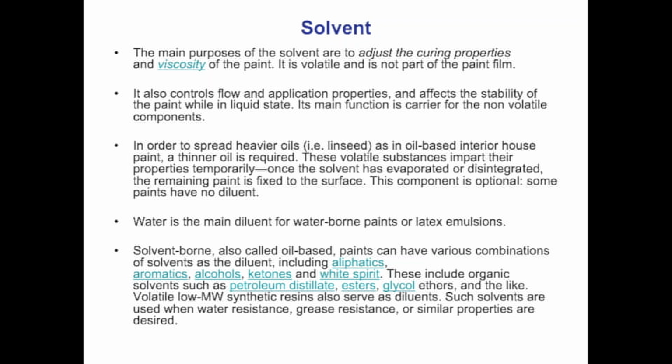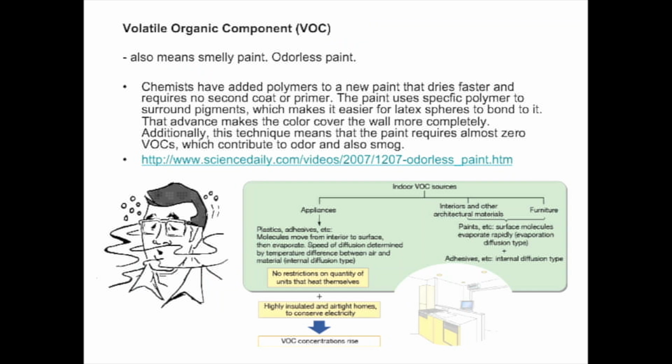Now, there's a lot of concern these days about volatile organic compounds. So for sure, a paint that smells includes volatile organic compounds, including the solvent that gives it an uncomfortable smell or feeling when you have a newly finished paint procedure. So more and more countries in Europe and other countries, including the direction in the US, not only discourage but even prohibit the use of organic-based paints. That is why there's a lot of move towards solventless or powder-based coatings or even water-based coatings.